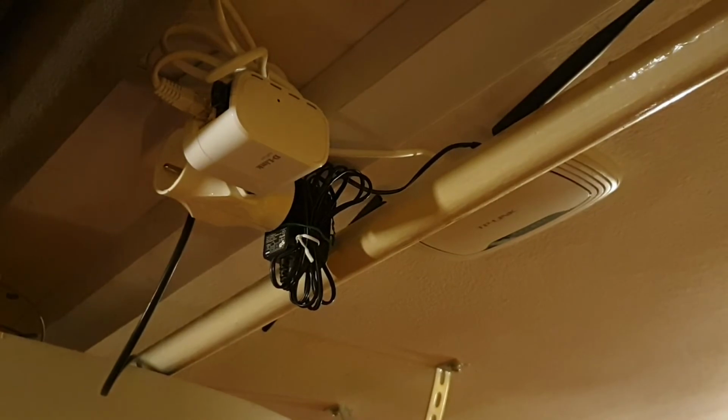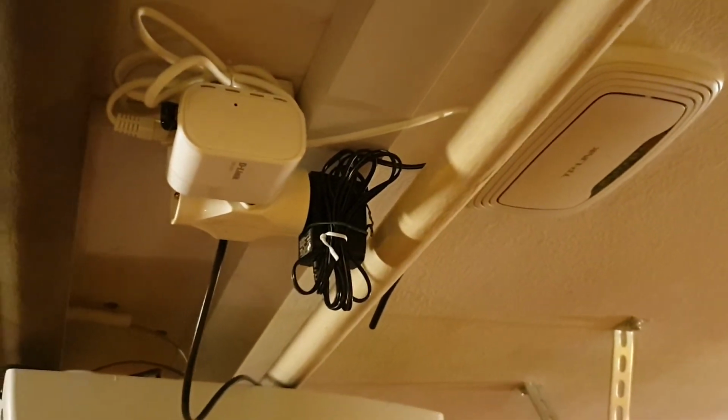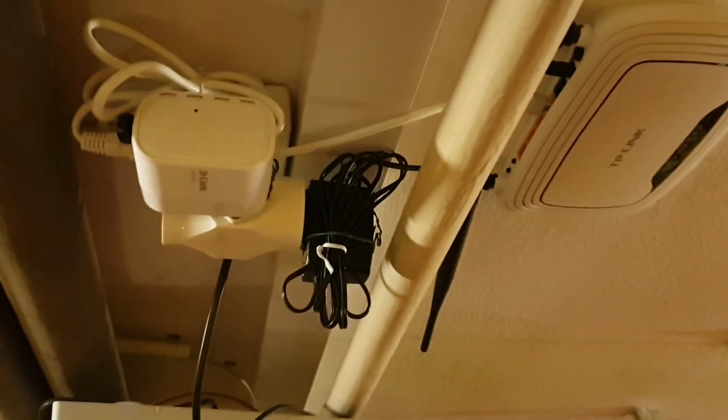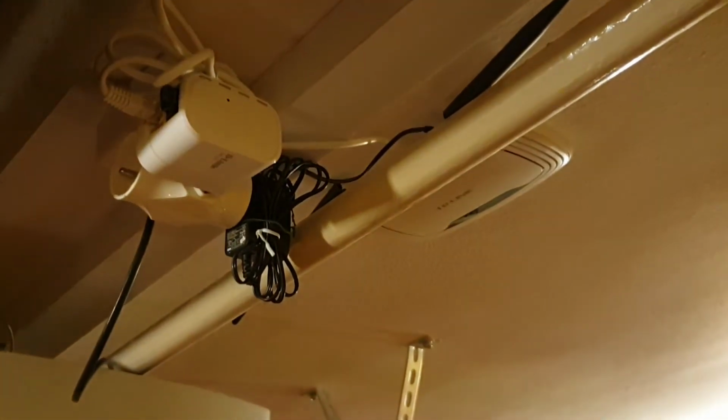And also it can pass that limitation that the Modbus protocol and that inverter has. That is, only one device can be connected to that Modbus 502 port at the same time. So it can surpass that, because I can forward that port from that D-Link router and use it from other devices. So I can either use it as a cache and tap to those files through the FTP, or I can forward that port and use it from multiple devices. Of course, I'm still limited, and if I would like to reconfigure that inverter from my phone and the application provided by Huawei, I will need to power it off or disconnect that D-Link router to be able to do that. But of course you won't do that every day, so it's perfectly fine.